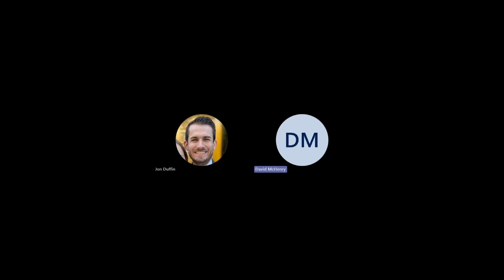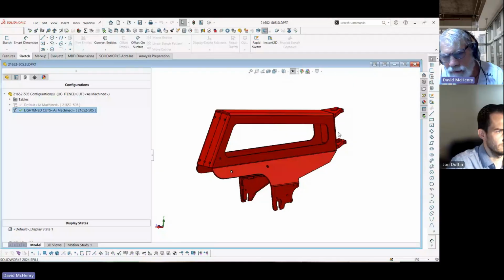And then back here, this is the pivot pin that it pivots on, and I'd probably do something similar there. And then the boundary condition would be to fix both of those shafts, basically, and then start playing with loads, but how to characterize the loads.